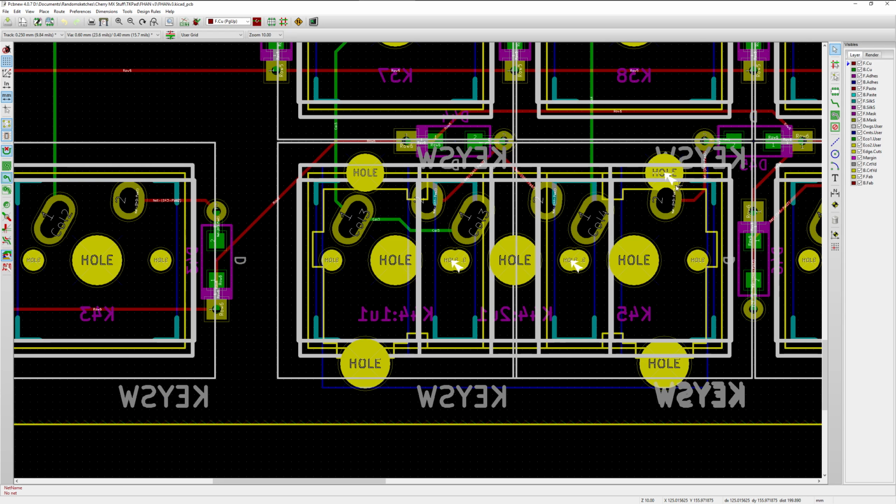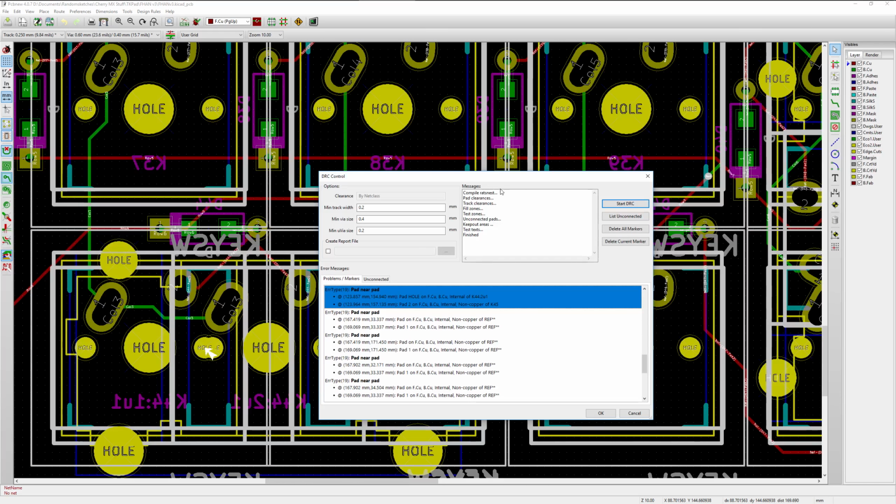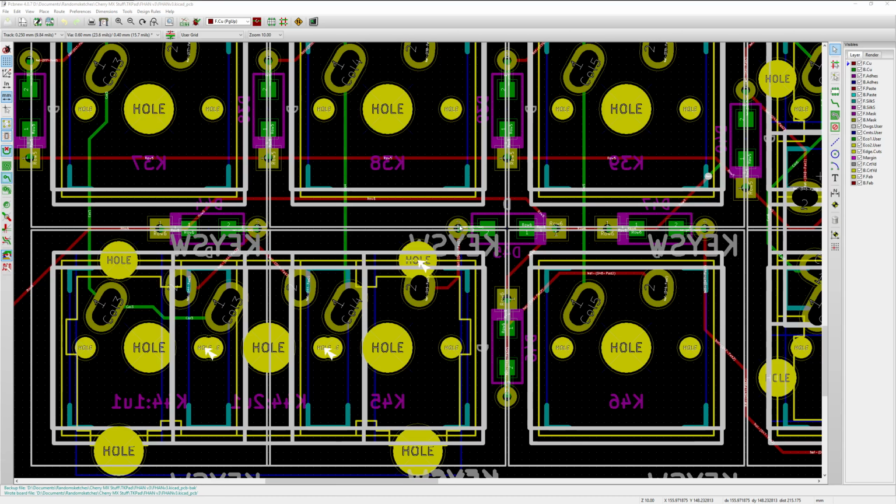And then it looks like the rest is all sorted. So I'm relatively happy with that. If there was any issues that needed to be fixed, they would be in red, critical. And I've had that before on the V2, so I'm really happy with that. Turned out really well. The previous errors that I had were ones where I hadn't connected the traces completely. So I'd clicked here, clicked there, but I hadn't double clicked. And when I clicked there and then onto the next point, it was assuming that it was just a single trace all the way across and it wasn't a connected trace. And so I had to go back and double click on every single one of the joints, which I've done this time.